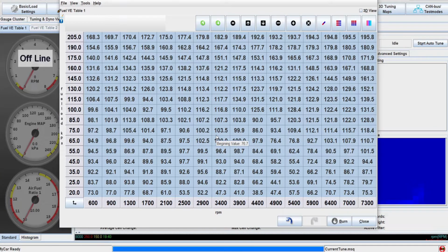The problem with this is that there are several places that need to have more fuel. Basically any calculation regarding fuel delivery. So all those places need to be multiplied, and not just that, retuned. We're talking about cranking, warm up, acceleration enrichment, all kinds of places. So that's why this method is not ideal. While technically this will run and drive, it may not start, especially if it's a cold day.